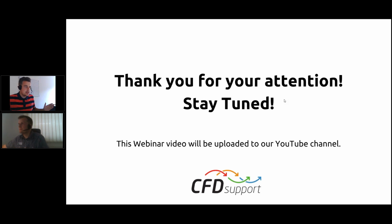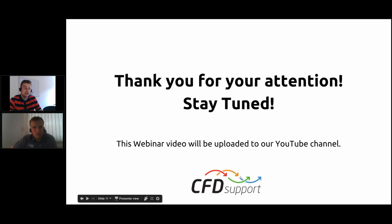Radek, anything to say? Well, as you saw, the usage of our software is really simple and straightforward. You load your geometry with a few clicks. You define the mesh. You set your operating point, and then you just click on Run All, and you will get the results. You get post-processing tools, which is really nice, and it is comparable with standard OpenFOAM, where you are not able to achieve all these steps.